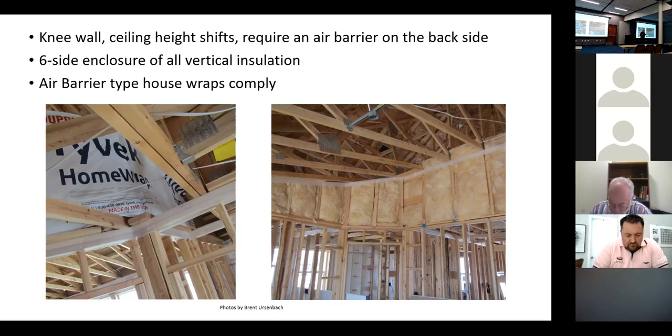I'm much more comfortable with an encapsulated attic with all the insulation on the other side of the roof sheathing than I am with an HVAC system up there in the hot attic.